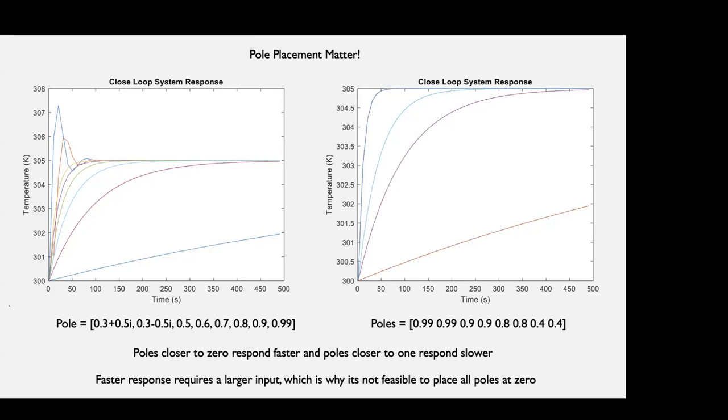That's a drawback of linear control. We talked about controllability, which is going from an initial state to a final state in a finite amount of time. That finite amount of time can be really large, it just can't be infinite. So if I choose 0, then my input is going to be huge and will do it, but it's not actually a feasible input response for your system. So you have to choose.